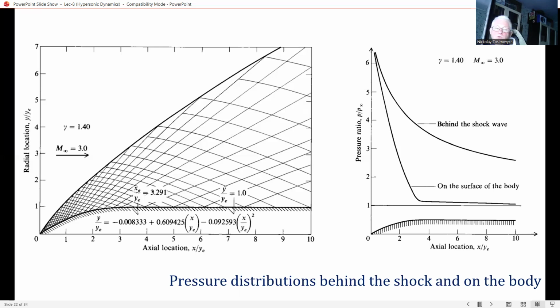However, the three-dimensional method of characteristics requires considerably more effort than its two-dimensional counterpart. In three-dimensional rotational flow, the characteristics are surfaces, namely Mach cone and stream surfaces.